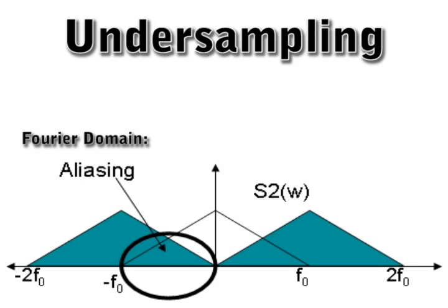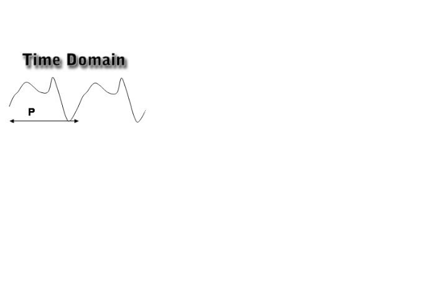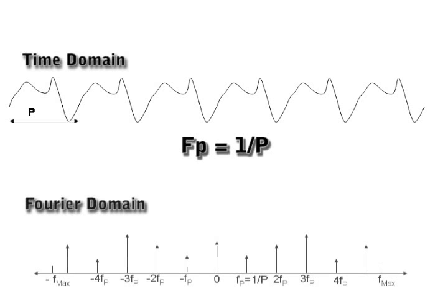According to the Nyquist sampling theorem, in order to faithfully reproduce a band-limited signal, the sampling rate must be twice the maximum frequency. Generally, this requires expensive high-speed cameras. In this paper, we look at the class of periodic signals and show how to go beyond the Nyquist limit while reconstructing such signals. It can be shown that if a periodic signal has a fundamental frequency of f_p, then its Fourier representation contains energy only in the frequencies that are integer multiples of f_p. This means that all periodic signals are sparse in the Fourier domain. We later will show how to exploit this sparsity in our reconstruction algorithm.